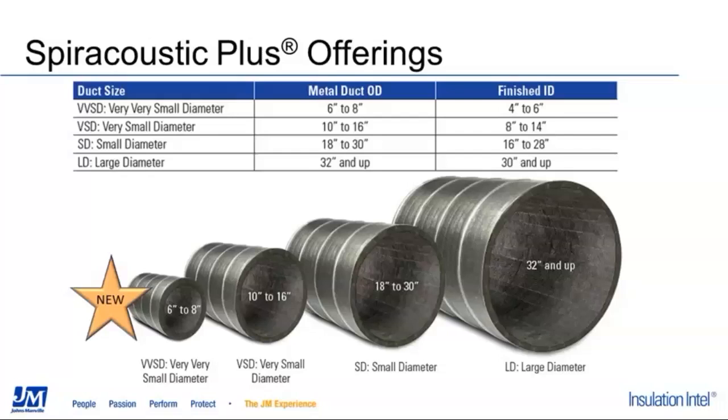The larger the duct size, the greater the variety of thicknesses you can use in the duct, as the smallest duct sizes don't accommodate the insulation thickness because of the lack of space. The greater the thickness, the higher the R value, and the better the acoustical control when necessary. Spiral Acoustic Plus Ductliner has been used in a variety of stadiums across the U.S. with ductwork that exceeds 96 inches in size.